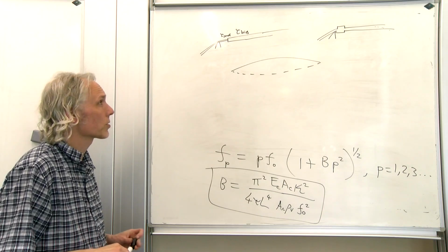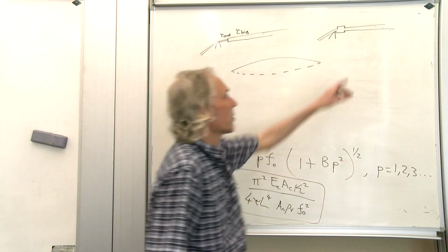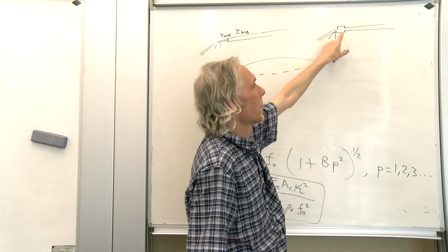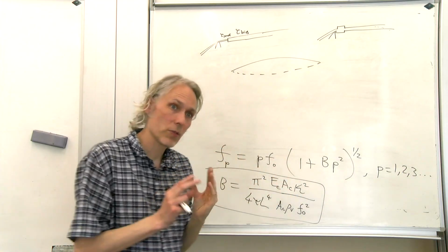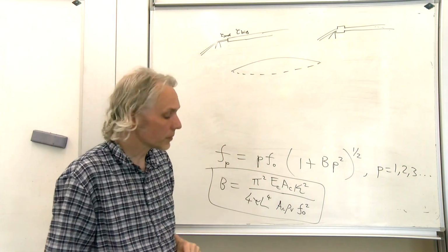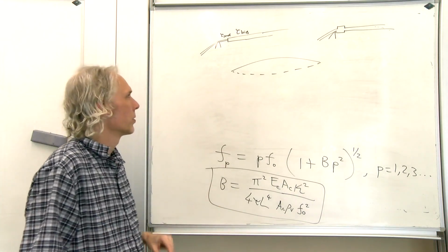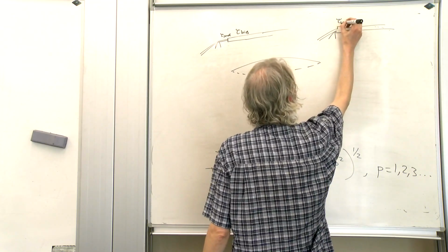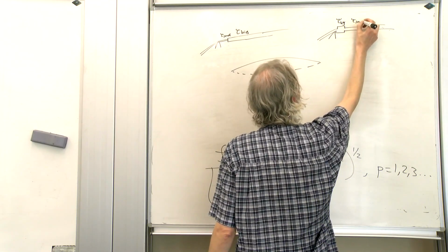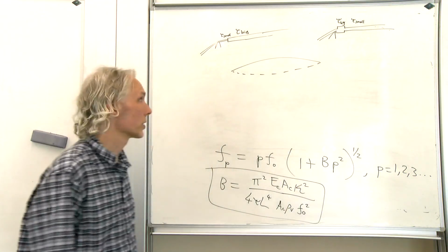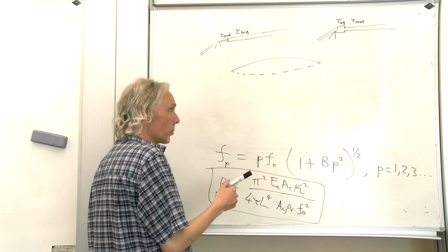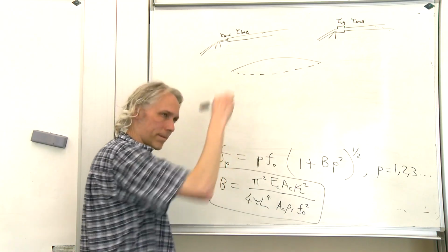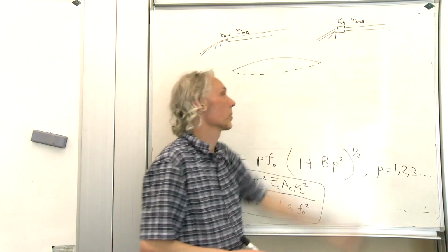So if you've got a bigger cross section near the support, then this is actually going to mean that for the same frequency on this bit of string and this bit of string, this bit of string has got to have a shorter wavelength for the same frequency. So if we consider this one where we've got a tau big here and a tau small here, it's kind of an easier picture to draw intuitively. So what that means is we're making the shape get steeper when we get to here.